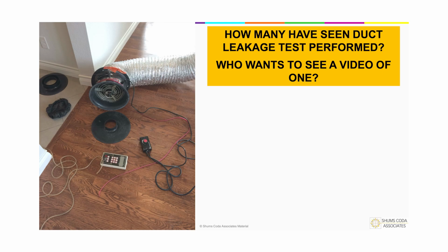Typically, if they are testing at the final stage, the ductwork is going to be leakier. It's not uncommon that you'll have more leaky ducts at a final stage as opposed to doing it at rough-in, just because there's more things that happen, right? You have everything pristine. If you have something installed in a building during construction, does it never get knocked or have something hit it and dent the ductwork? Because it always stays pristine, right? So that's kind of what he was referring to there.